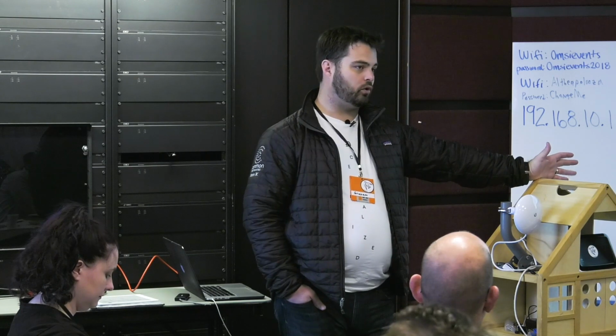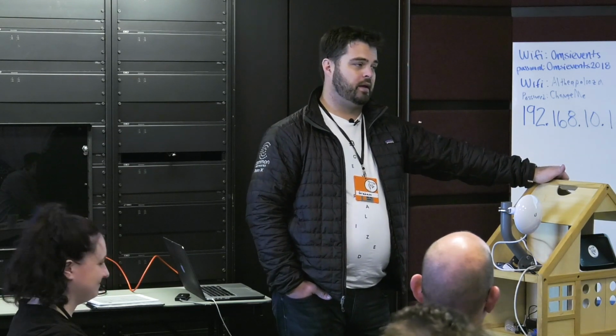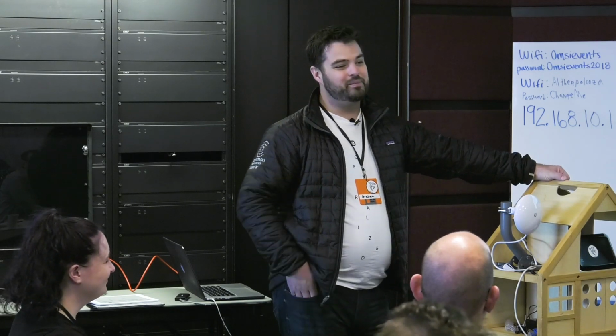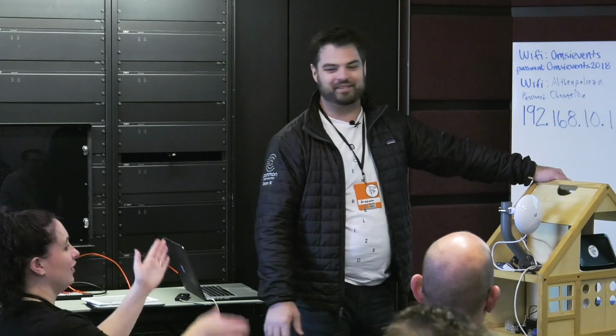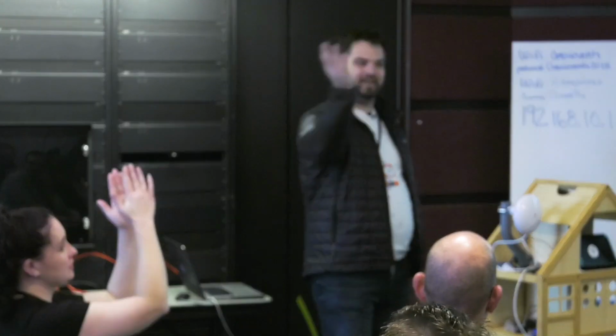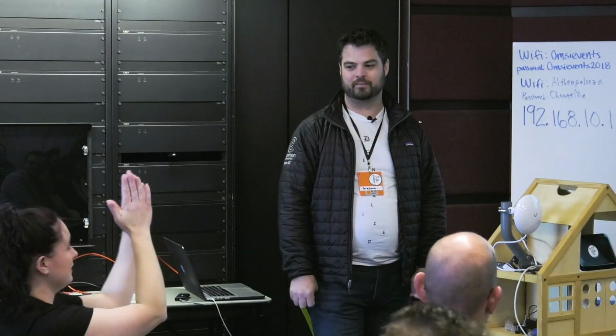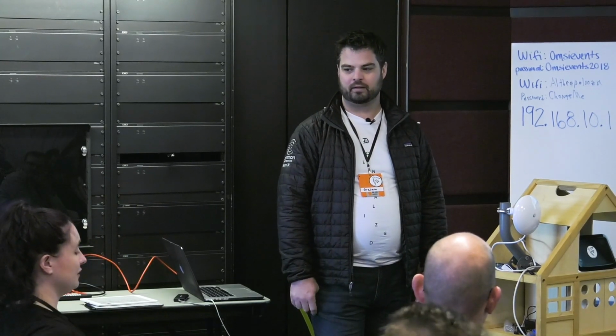The tree would do the same, I guess. So if you wanted to use a tree to hold one of these pieces of equipment, I've seen people do that. It seems pretty risky to me, mainly because trees grow and turn and fall over. And they sway. The higher up you get, there's quite a bit of sway on those. So you want to put a sector antenna if you're going to do tree things.